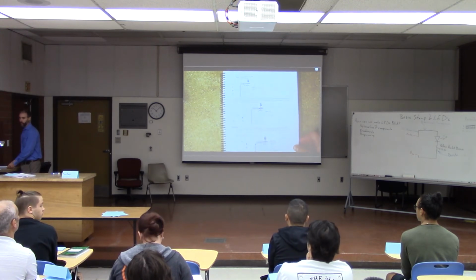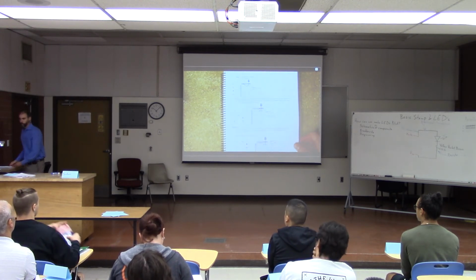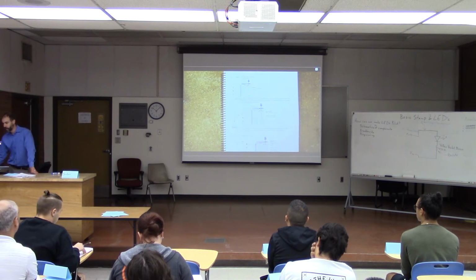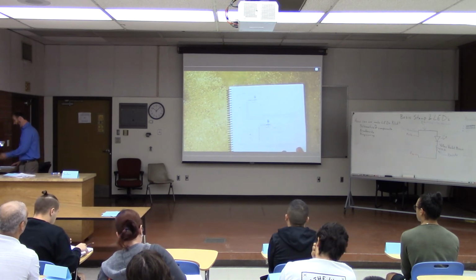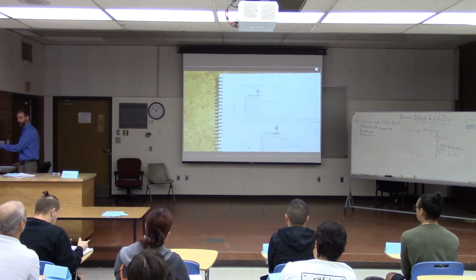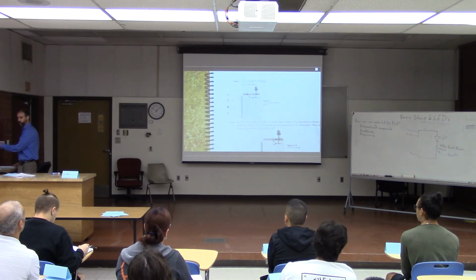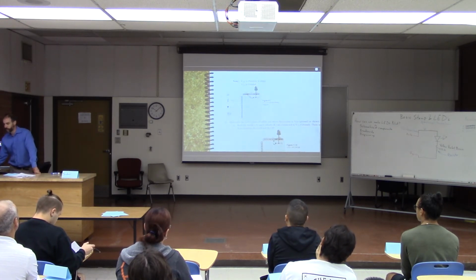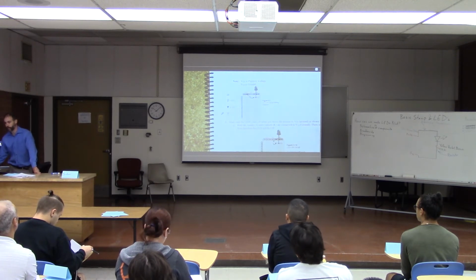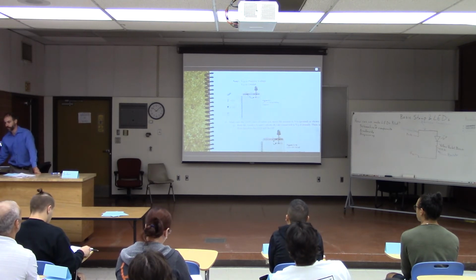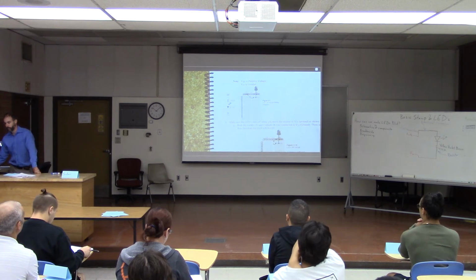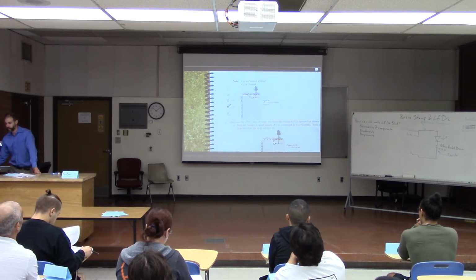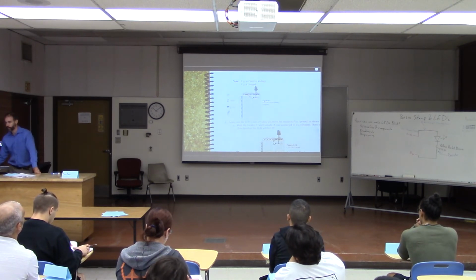Then it shows you how to start hooking up these circuits. On the left-hand side of the book, it shows you a circuit diagram. So this is like the first diagram that I drew on the board. One side of the resistor is connected to VDD, then it's going to the LED, and then the other side of the LED is going to VSS.